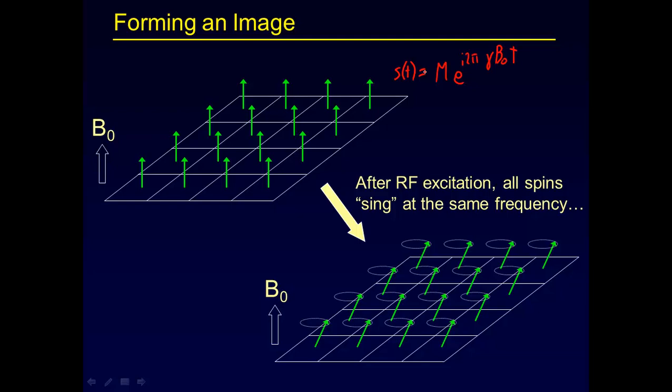Well, it turns out that this signal is polarized in a certain way. And so you actually are getting two different signals that you're able to pick up. And if you treat one of them as a real part and one of them as an imaginary part of a signal, I mean, of course, they're both just real measurements, right? But the math works out just great here that if you treat one of them as the real part of a signal and you call the other one the imaginary part, you put them together as one signal, then this is actually what you receive. You receive a complex exponential like this.